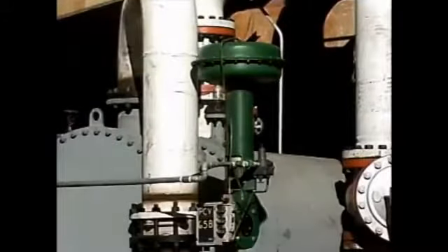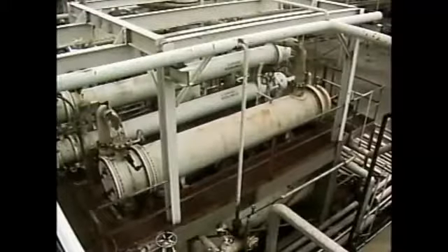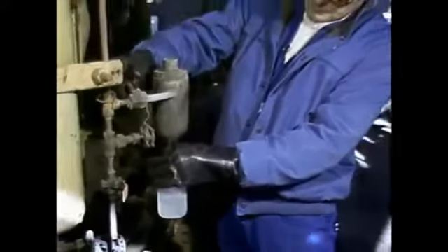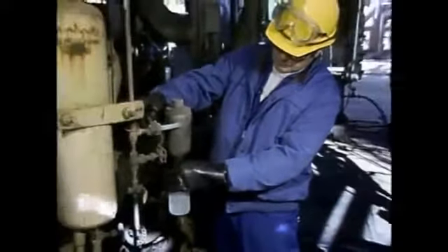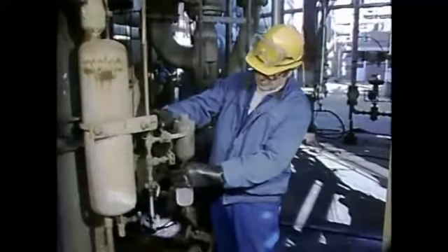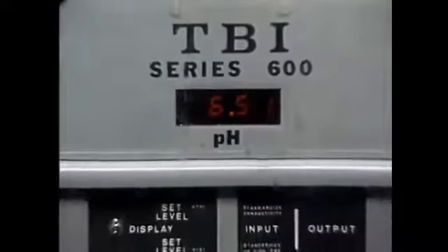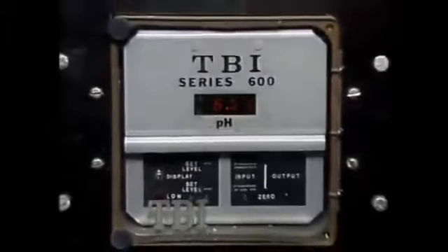An abnormal cooling water temperature could be an indication of a problem with the control system or with the cooling water system. Contamination in a condenser may be caused by a tube leak in the condenser. One way to check for contamination is to take a sample of the lower pressure fluid and test it for the presence of the higher pressure fluid. In some cases, contamination in the sample can be seen. In addition to sample test results, conductivity and pH readings of cooling water may indicate a tube leak.